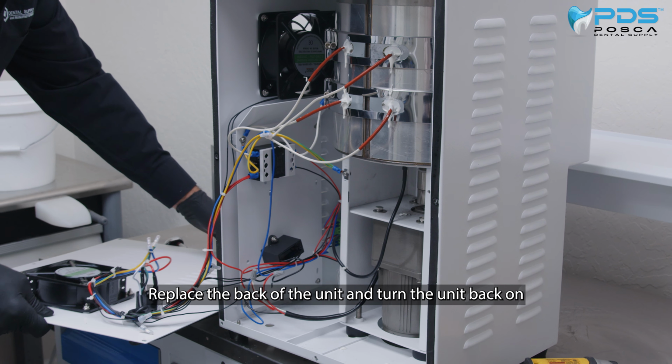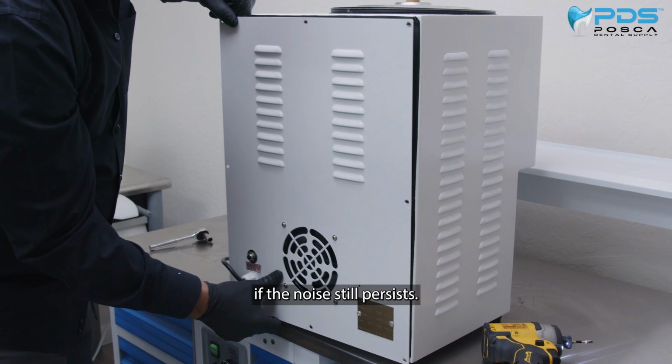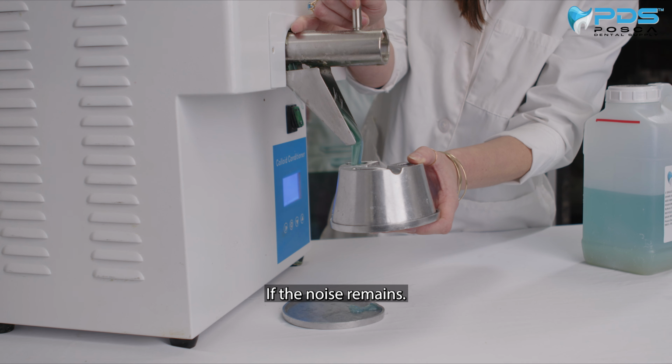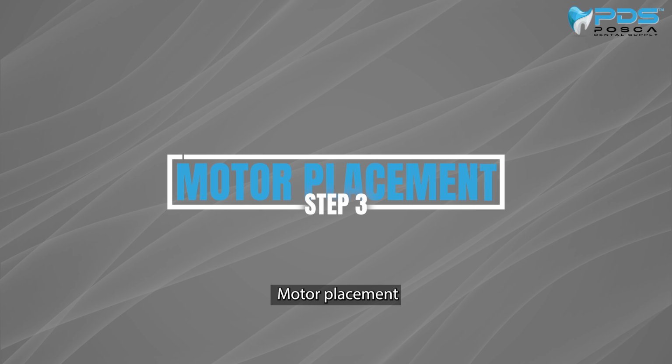Replace the back of the unit and turn the unit back on for a couple of minutes to check if the noise still persists. If there is no noise, refill the unit and run a cycle as normal. If the noise remains, please move on to the next video. Motor placement.